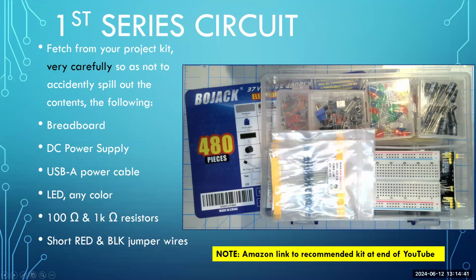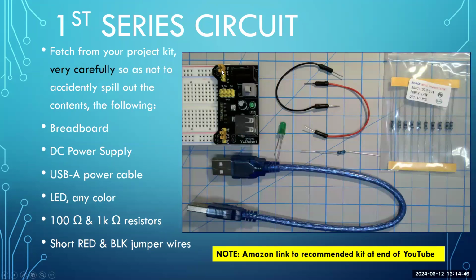Now let's get further into pulling these things out and what they're going to look like. This is what they're going to look like. There's your short jumper wires, stainless steel pins on either end, one red, one black. There is your LED, and notice the LED, you choose whatever color you prefer, but notice one wire is long and one wire is shorter. That has a great deal to do with how you go to put it onto your breadboard. Then we have a single 100 ohm resistor. There's your 100 with the omega symbol right there. Only pull out one of these.